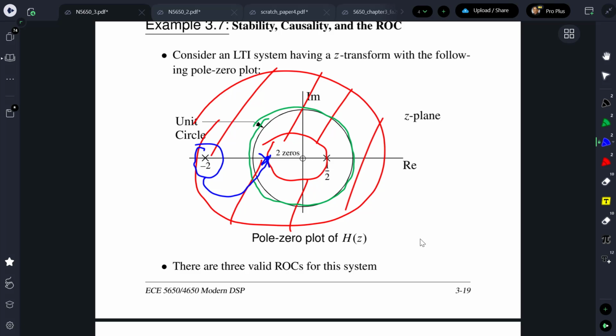So it's not that the path is non-causal. The path is an FIR system, so there are no denominator terms. It's all numerator stuff, but we'll have positive powers of Z in that Z transform. If we try to invert that channel by putting those zeros into the denominator to make an equalizer for the channel, then we'll be non-causal. That's where we have the problem.